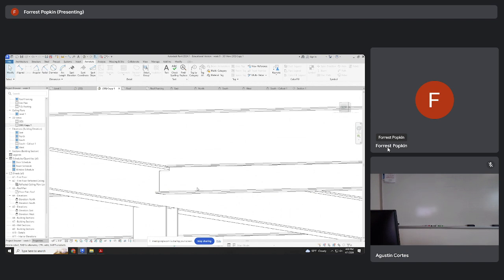If you just have a concrete floor that's 4 inches thick, the question you have to ask yourself is how is that being supported? Even so, if it's a wood building, you still have gypcrete, which is a pourable layer. They wouldn't have any idea why we'd use something like gypcrete or concrete, even in a wood building. What do you think that might be? There's a few reasons for it. What is this material? Gypcrete is a gypsum product, which is in drywall, that's mixed with concrete, so it's a little bit cheaper. It doesn't have to be structurally robust, but it just helps keep something level and hard.